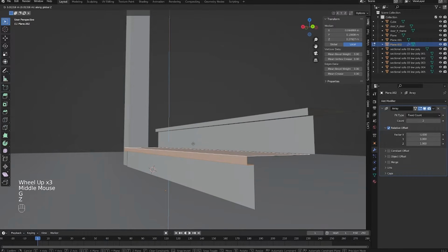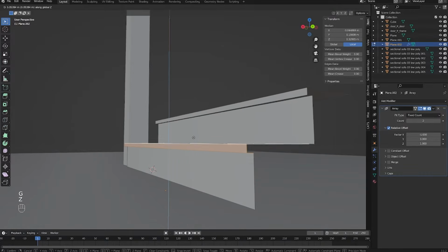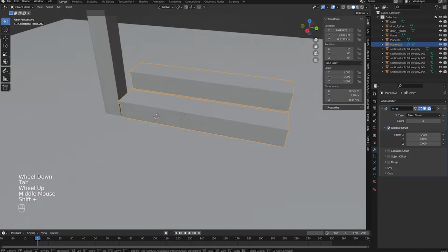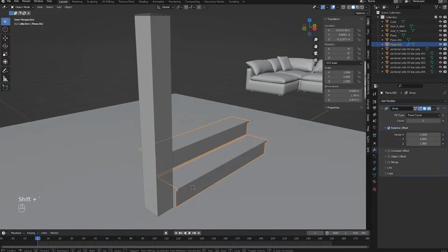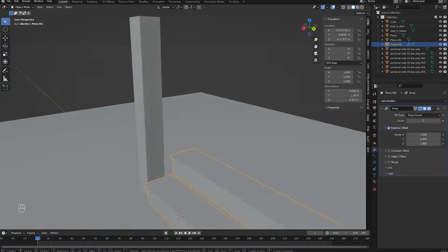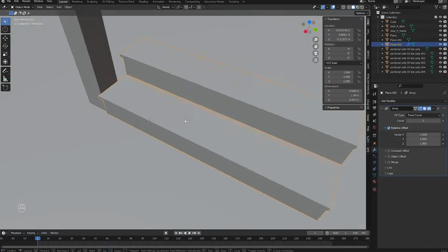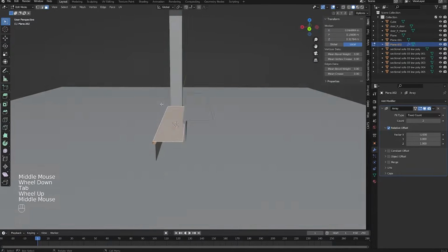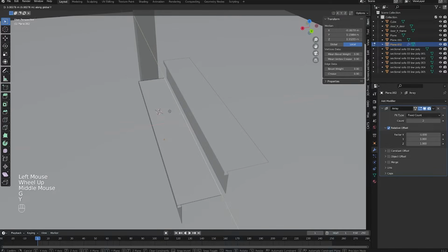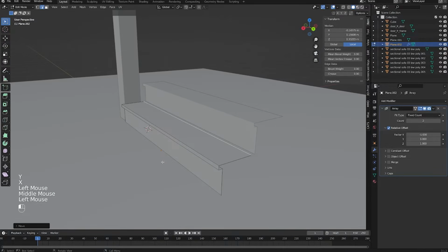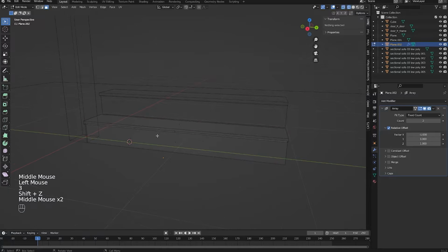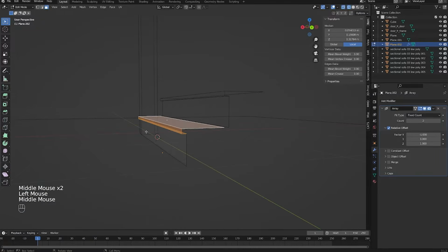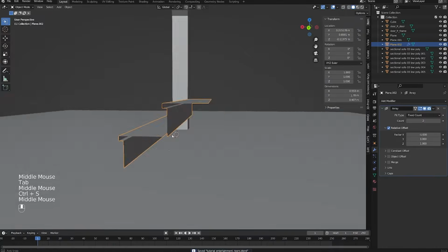and I'm going to press G to move, Z to lock into the Z axis, bring it up. Let's walk around here by pressing Shift tilde. This seems like some real steps, kind of. Seems a bit big, actually. Maybe if I grab this edge, press G, lock the x-axis, bring that in, and then I can Shift Z, select these faces, G, Z, and that's pretty good.